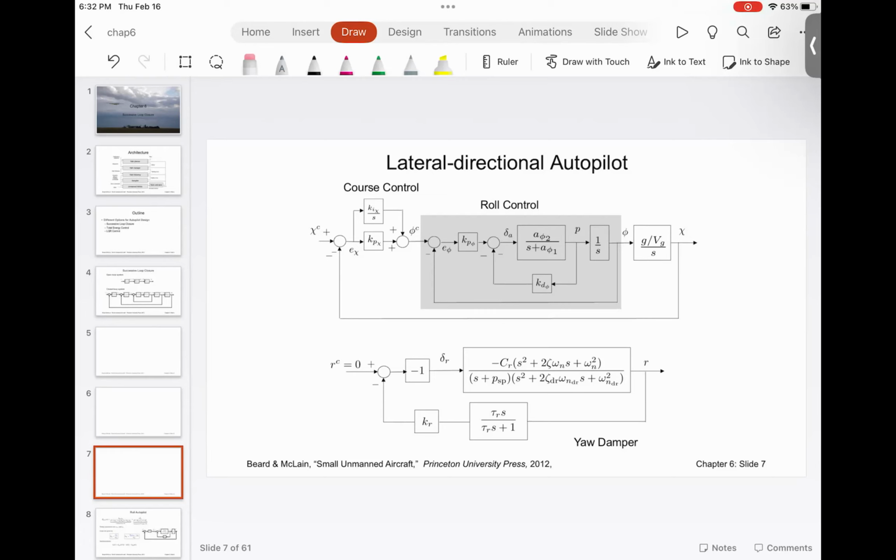So to compensate this unwanted motion, you have the rudder. That rudder continuously compensates this motion, and so we add a yaw damper. And I want you to understand that the equations you see will be in the form of a spring mass damper system.